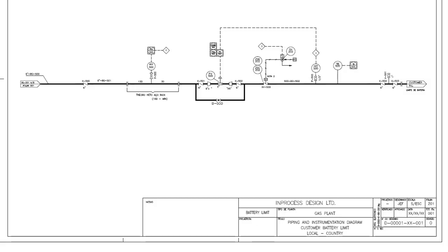For instance, you had set the engineering hours to do a P&ID, you had added that in the documentation list, and you did the process flow diagram and identified the piping, instrumentation, and control that you need to add to do your scope of supply, and you had used the line list to identify the lines that you use, and the instrumentation list to identify the instrumentation numbers available.